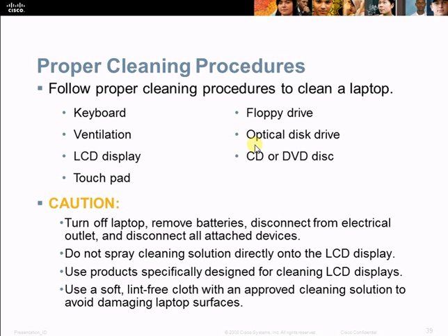Whenever we do any type of cleaning of the keyboard or the monitor, we want to turn off the laptop and remove any batteries, because remember, if the battery's still in there, it's like it's plugged in. Do not spray any cleaning solution directly onto the LCD display or the keyboard. Always use a soft, lint-free cloth when you're cleaning your computer.